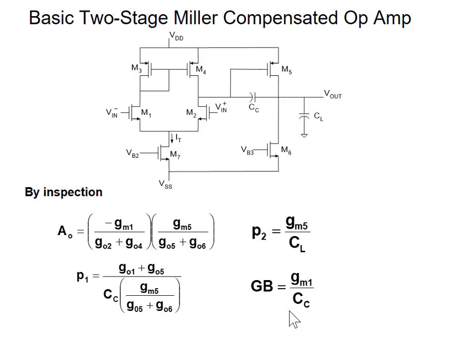Dr. Tips, talk about phase margin. Do we need phase margin? It depends which criteria. Did we need phase margin to put the poles to avoid overshoot or ringing? No. Well, we assume it's an all-pole system. If it's an all-pole system, we don't need phase margin.